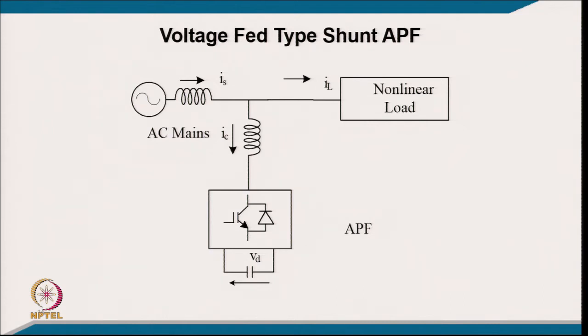Moreover, when the switch conducts, either the IGBT will conduct or the diode will conduct. The losses of either the IGBT or the diode are there, so losses are also reduced here. Moreover, here you do not need the shunt capacitor; you need the interfacing inductor, and in many situations, in place of the interfacing inductor we might have a transformer, if you are using this shunt filter at a different voltage at which it is injecting the compensation. So, maybe the leakage inductance of the transformer can also do the job of the interfacing inductance. Because of these reasons, this has taken a lead in technology as well as development. So now voltage source converter based shunt filters are more popular.